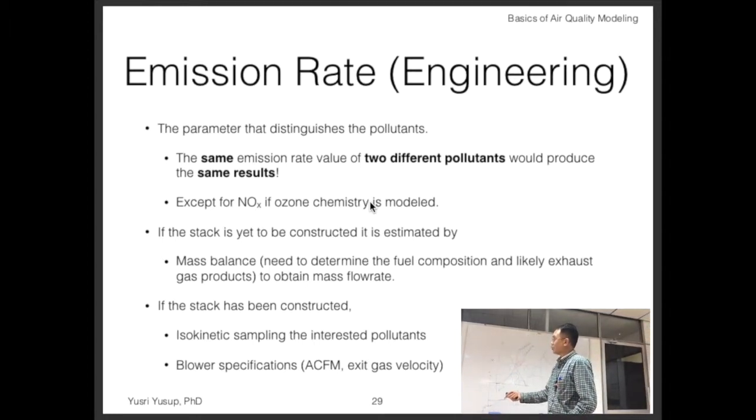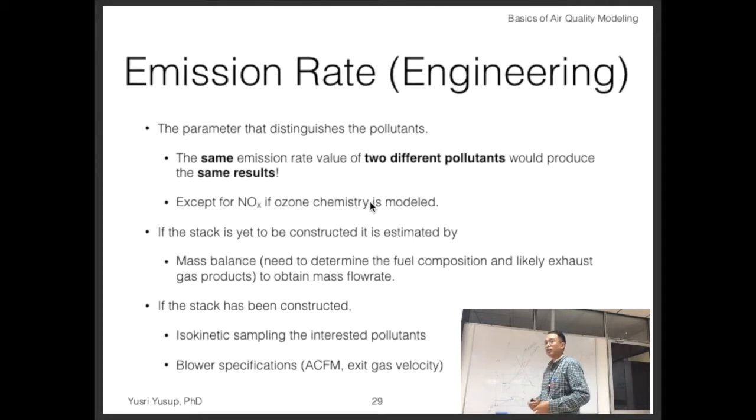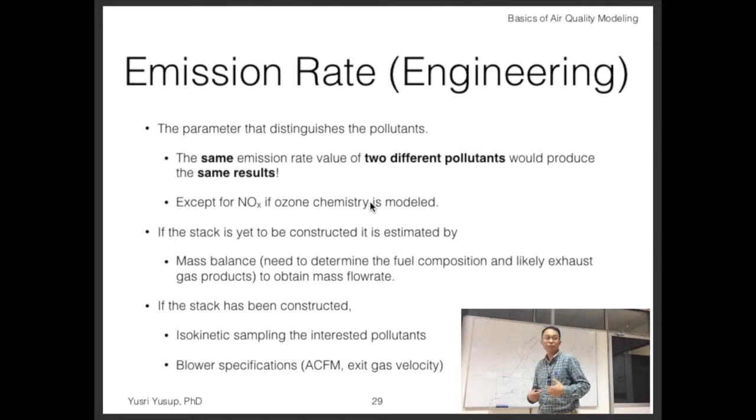Now, if the stack is yet to be constructed, like most of the time you want to run an EIA, Environmental Impact Assessment of an area. A company wants to build a factory with a stack, and it wants to assess the environmental impact. We don't have any values from there because it hasn't been built yet, but we need to predict, right? So that's where we need to use the air quality modeling, like this one, so that we can guess what is the potential impact based on the design given by the company.